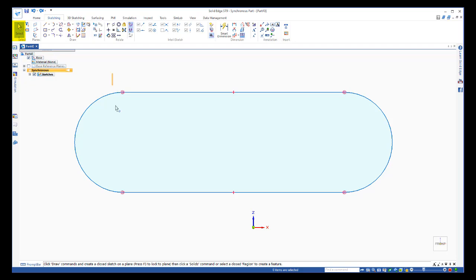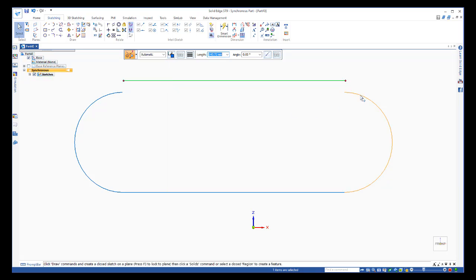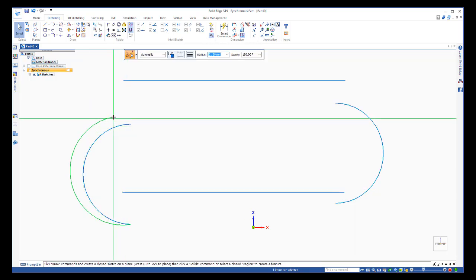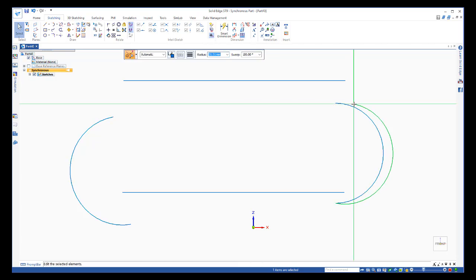If I go up to the select button, I could box pick and delete all those constraints. And the constraints I have, the geometric constraints, are connect and tangent. Once they're highlighted in green, I can hit delete, and I could hit delete the plus signs also. And now, if I touch on this geometry, I can just pull this apart. There's nothing holding it together. And I could grab parts of this arc and just modify that.